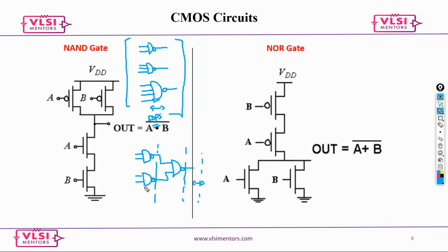These two will take about 30 ps propagation delay, and this one will also have a 30 ps delay. If you end up adding one inverter here, and I'm not verifying the functionality now, just explaining, say that is another 10 ps, you would end up with a minimum of 60 to 70 ps delay overall.